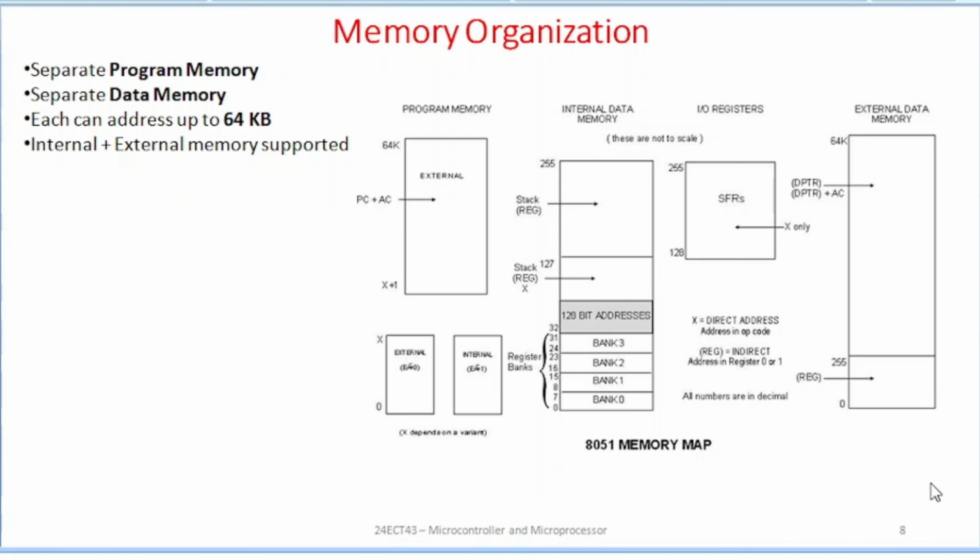The program memory has a 16-bit address, and any particular memory location is addressed using the 16-bit program counter and instructions which generate the 16-bit addresses. On-chip data memory is smaller and therefore quicker than program memory, and it goes into a random state when power is removed. On-chip RAM is used for variables which are calculated when the program is executed.